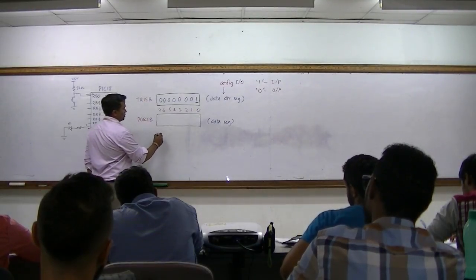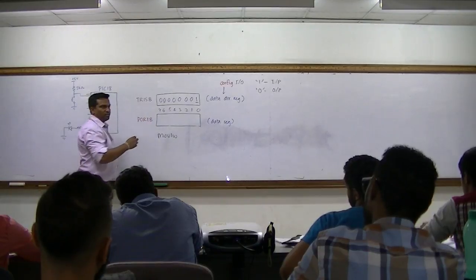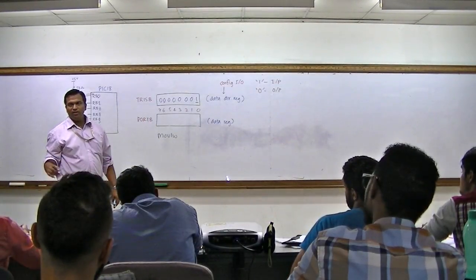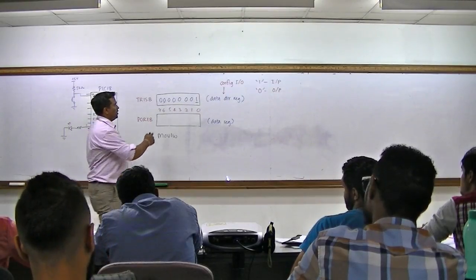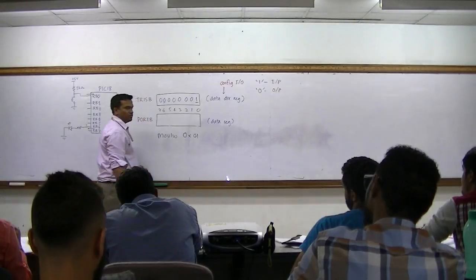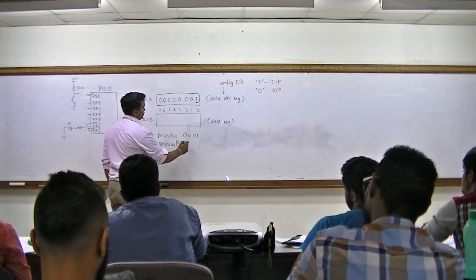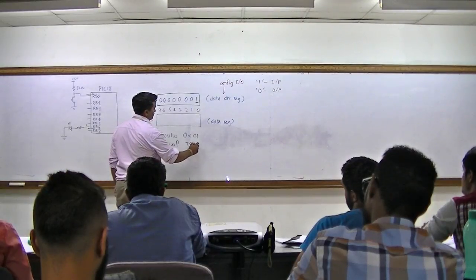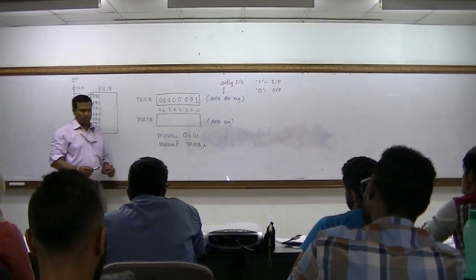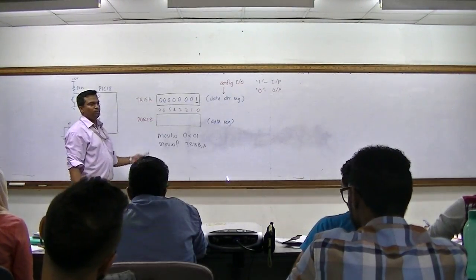You actually use all these ports like a normal file register. Just treat them like a normal file register. Nothing great about it. So what is this in hex? 1. Just move it to DDRB through W. Move to DDRB. So this performs the configuration.